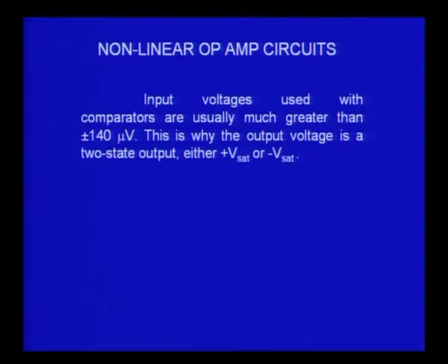So if I have one of the inputs at a particular voltage, in this case at 0, when the other voltage goes plus or minus 140 microvolt, the output will go to plus or minus VCC, either plus 14, minus 14, or whatever is the case.